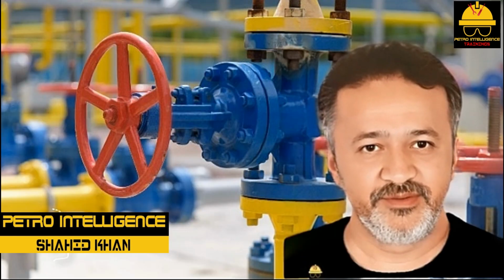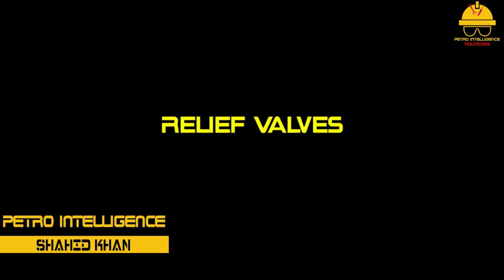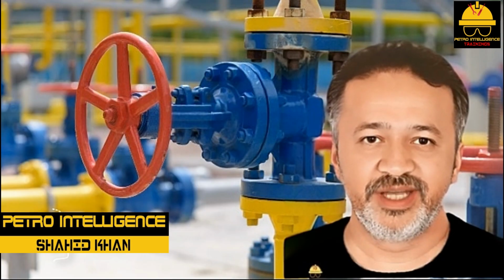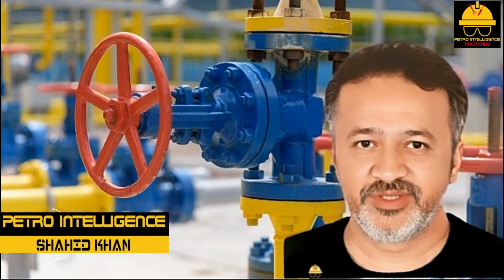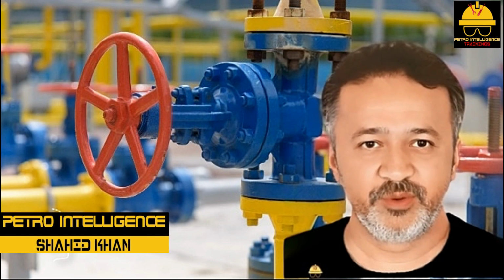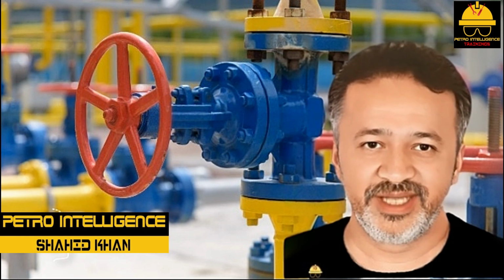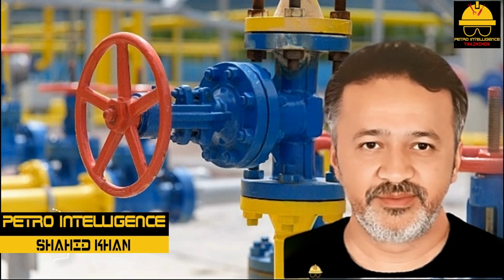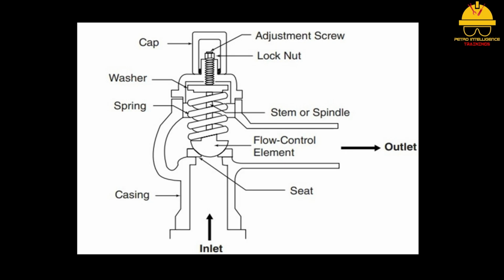Relief and safety valves. Relief valves. Relief valves have been engineered to respond automatically to sudden increases of pressure in liquid services. A relief valve is designed to open at a predetermined pressure. In a relief valve, a disc is held in place by a spring that does not open until the system pressure exceeds operating limits as shown in picture.